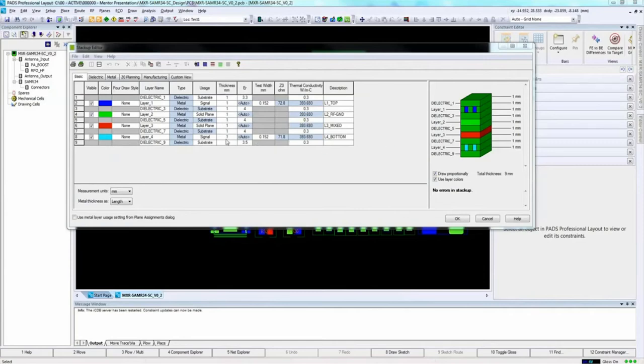So as I mentioned previously, a complete ground plane in high-speed designs is really essential. Additionally, a complete power plane is recommended as well, like we have here. And the best solution would be for every voltage to have its own layer and its own ground plane. But of course, that can be very expensive, and we would have a huge number of layers if we did that.